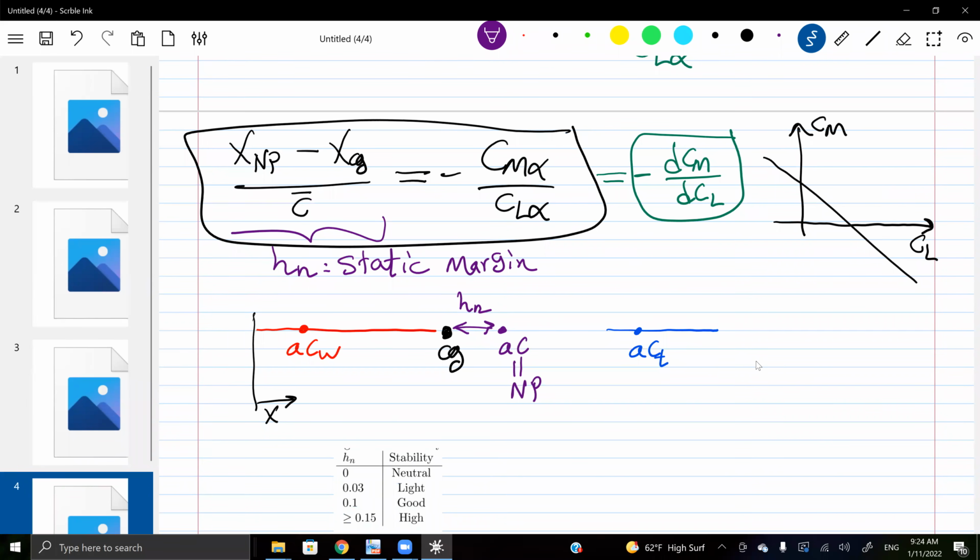So, okay, real quick regarding a canard fit stabilizer, would the contribution to the CM alpha be positive? Yes, very good. Yes, exactly. The canard will give you a positive CM alpha. So the canard is typically an unstable configuration, and you will need a flight controller to stabilize it. It will not be naturally stable. Yes, you're right. And in addition to that, you wouldn't have a downwash. Yes, you will have an upwash.